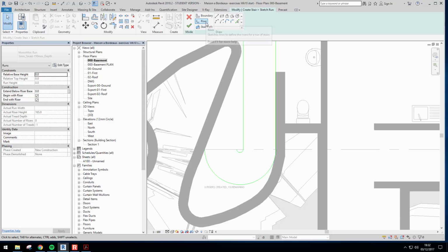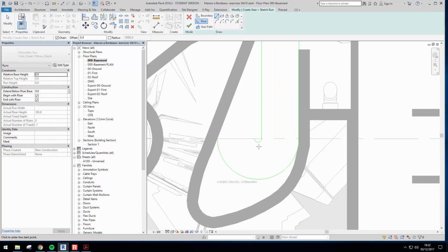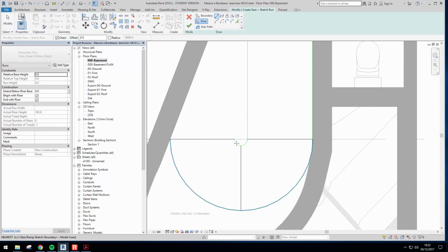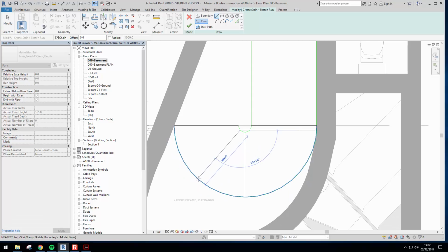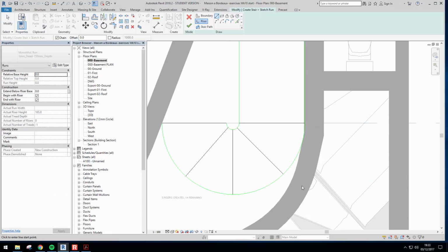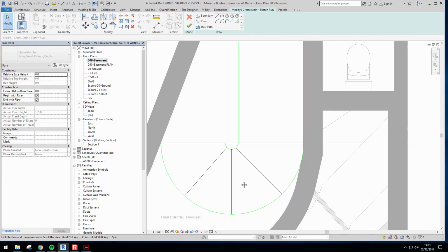The next we're going to use the risers. So first of all we're going to select the riser tool and we're just using the straight line. We're going to just do the curved element, so the spiral element. So we draw a line there where we start, and then we halve it, so we just pick the point, and if you hover around and select sort of halfway through, it doesn't have to be exact, and press escape just to get out of the chain mode, and again on the other side, and press escape a couple of times and then you should have 4 segments.